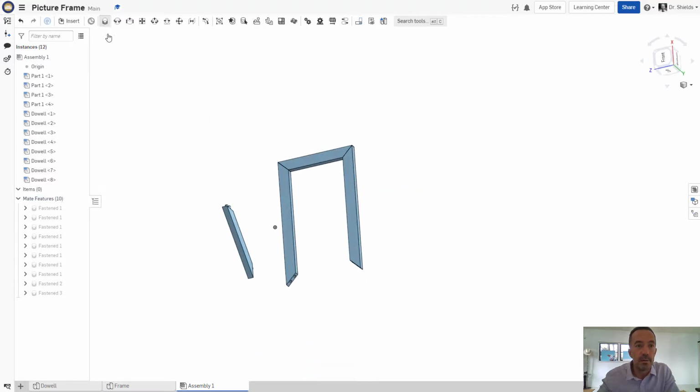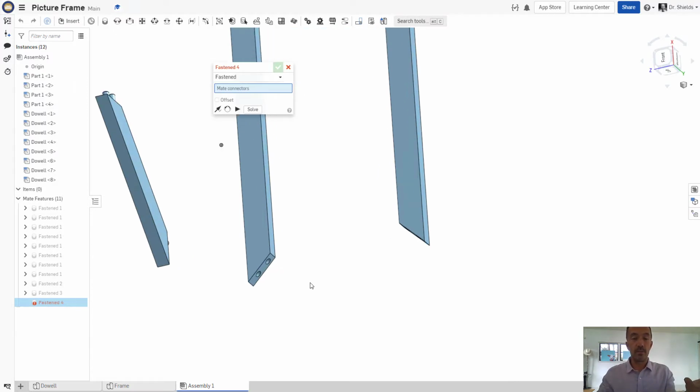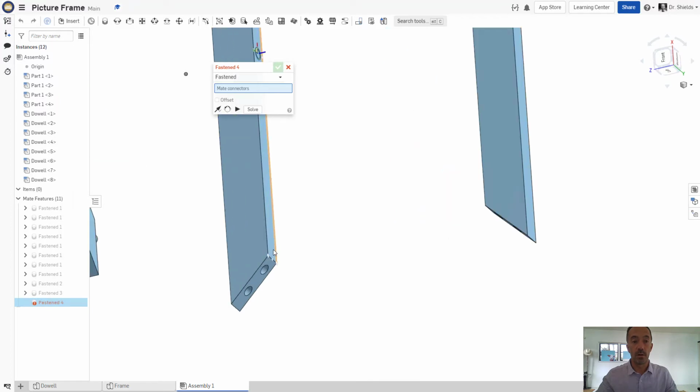All right, last one, fasten mate. So by the way, that shouldn't be mysterious. What I was doing is you can flip the primary axis. So when you do a mate connector, sometimes you have 2 primary axes aligned. Flipping those just aligns them this way or this way. Or I can actually reorient my secondary axis, and that is, so I've got these 2 aligned, and then am I flipping around? So my secondary axis is, I've got maybe this is aligned, and then my thumb is the secondary axis, and do I want it this way or this way or this way? With those 2 options, you can usually make just about anything you want to work look good.